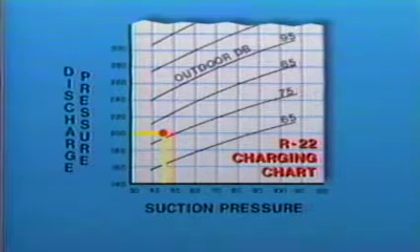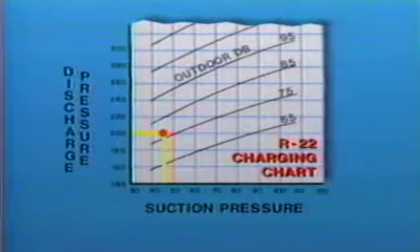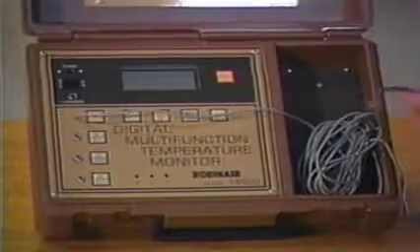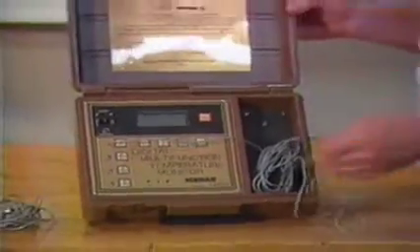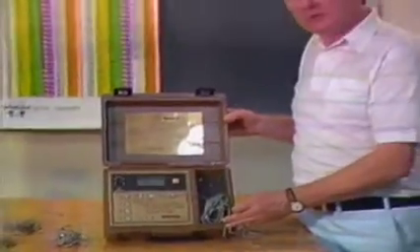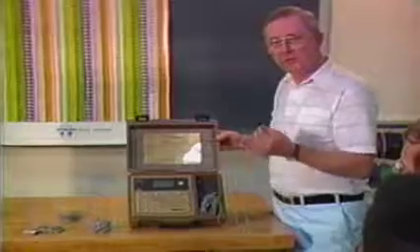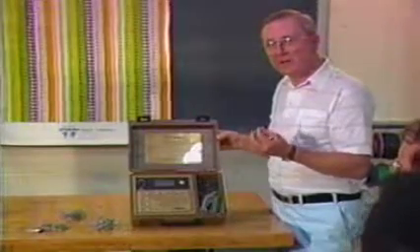The manufacturer will specify the boundaries for the head and suction pressures for a given situation. The 4-lead temperature tester, of which I only have one lead connected into this particular tester, is one of the very popular instruments that we use in the field. Reason being is because it's very accurate and very fast to respond.